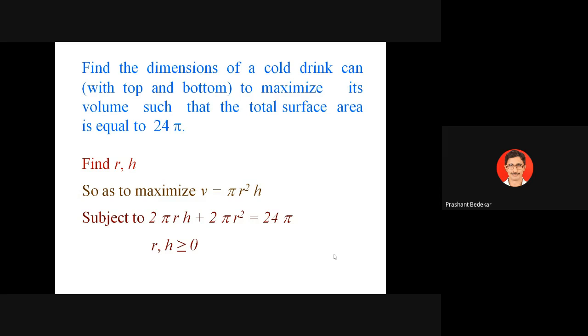So if you have a nonlinear inequality, first convert it into less than or equal to type. After that, whatever you are having on the right hand side, transfer it to the left hand side so that the right hand side will be 0. And for an equality constraint, there is no problem. If you have anything on the right hand side, transfer it to the left hand side so that the right hand side is equal to 0. So this is an additional thing that we have to do. Before applying fmincon, all the nonlinear constraints should have right hand side equal to 0.